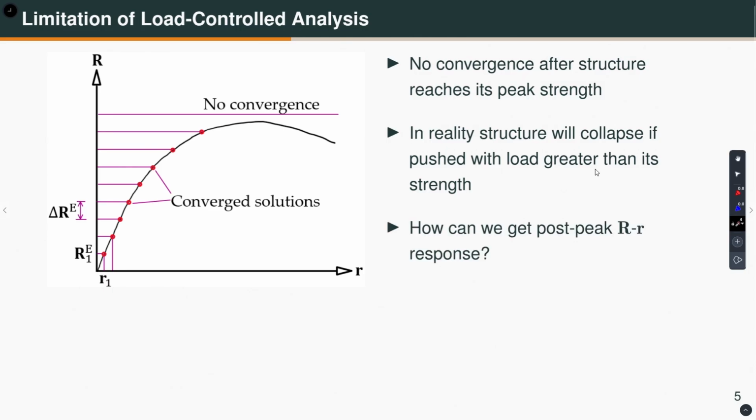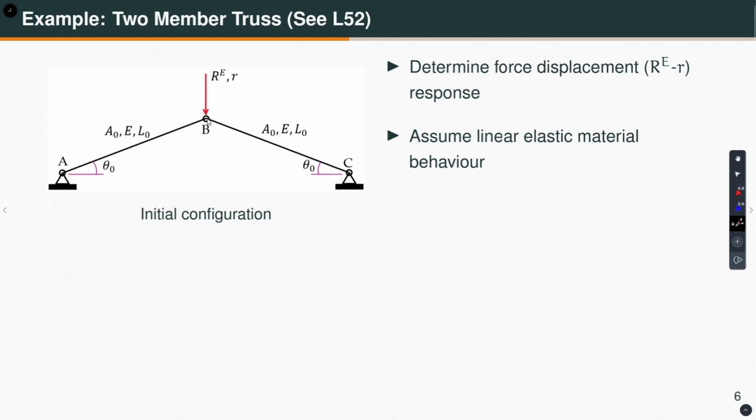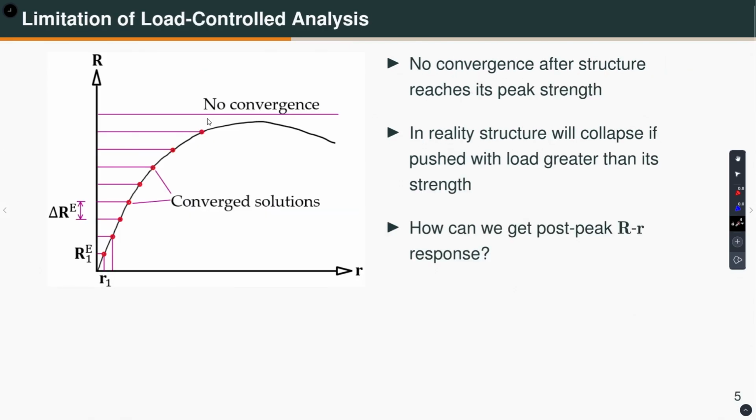So, the question is, how do we get this post-peak behavior? Because often we are interested in the post-peak behavior. Okay? So, especially in earthquake resistant design. So, how do we get this post-peak response? Okay? So, that is where we have to do displacement control analysis.